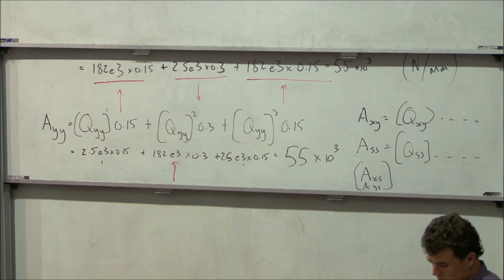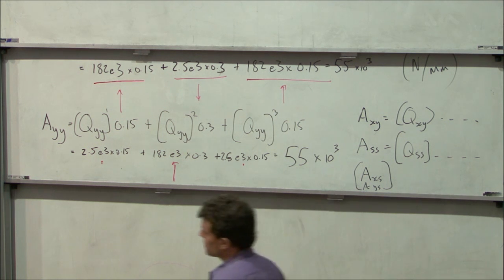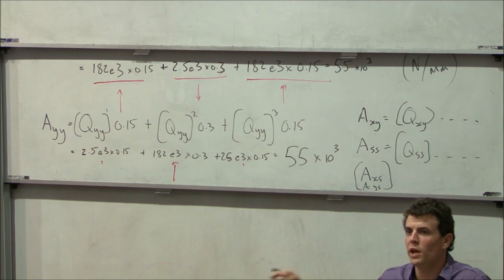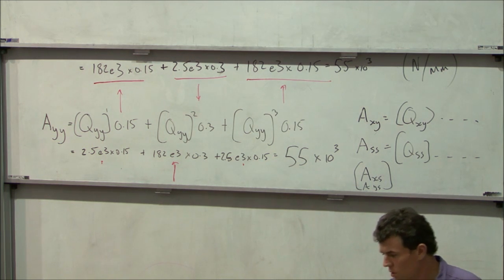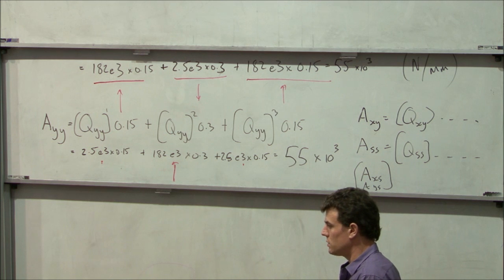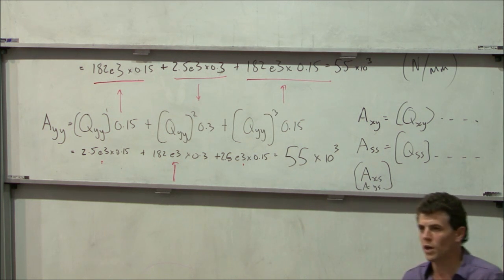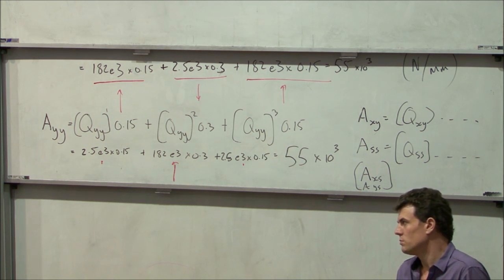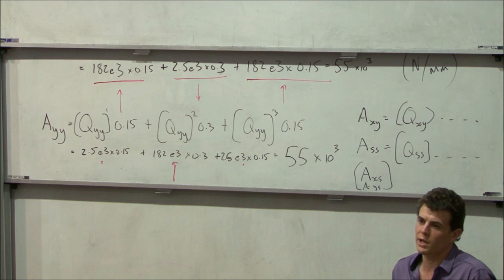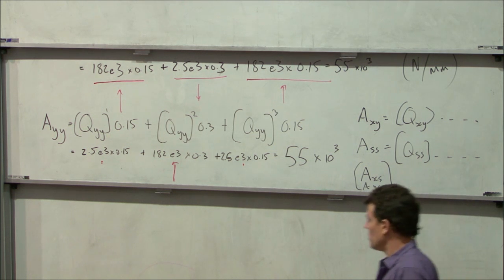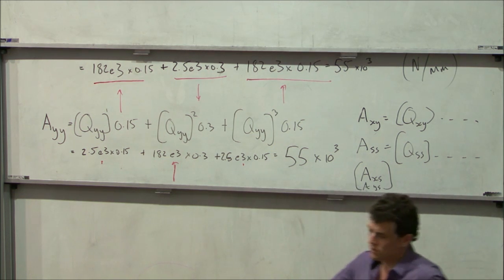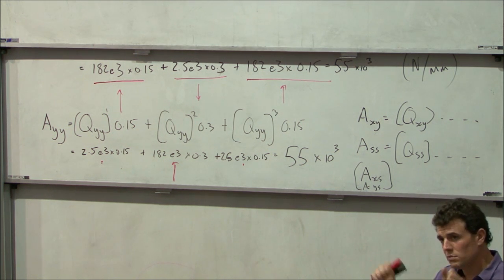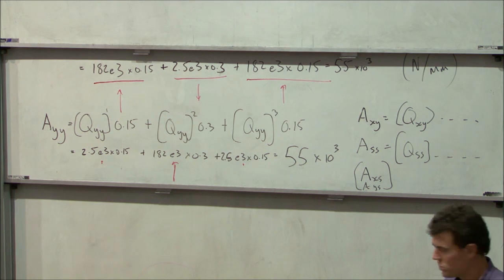Okay. So in practice, what this tells us is the A matrix tells us the magnitude of the in-plane stiffness. With normal materials, if we've got a modulus like E, there's really no difference between the in-plane and the bending stiffness. The in-plane modulus is determined by the Young's modulus, and the bending stiffness in part is determined by the Young's modulus as well.